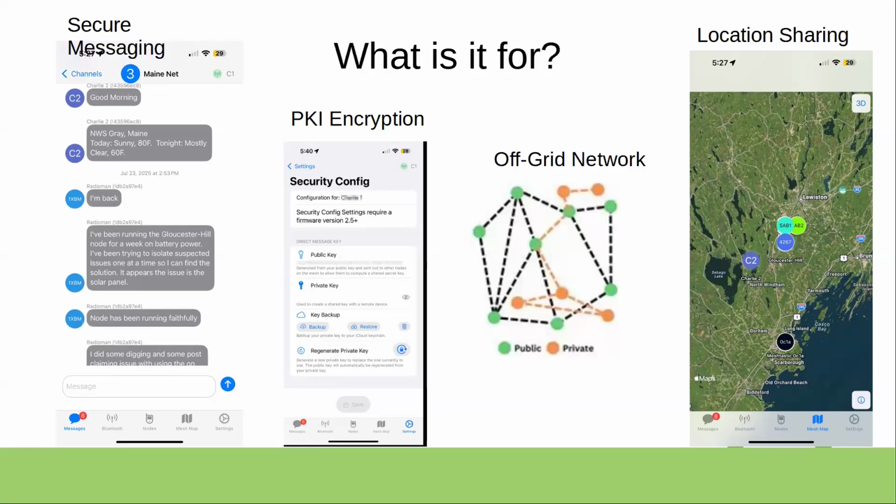So let's say we all have a node and only 3 of us are on the same channel, the same key. If person B goes to send a packet, even though that other node doesn't have the encryption key, it is still going to help in the bigger mesh and forward those packets on. You can turn that off if you don't want to be part of that. But that's a really big piece of Meshtastic: the more nodes, the better. Even if you're not friends, even if you haven't shared encryption keys, you can still use their piece of infrastructure to get your messages across. It's very similar in nature to APRS, if only APRS had private chat rooms, so you can channelize it and you don't have to be flooding everything to talk to your buddy.